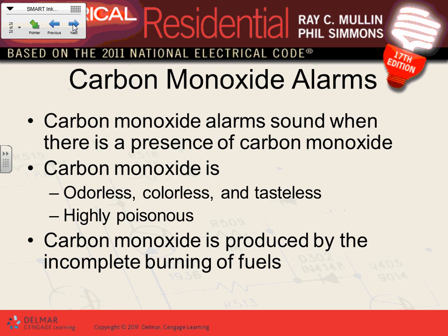Carbon monoxide detectors, guys, detect for carbon monoxide. I think in Minnesota, it's required at least once in the building. One of them in the whole house, in dwelling, it's required once. It could be plugged in or hardwired, but you have to have 2 sources of power for it. If it's plugged in, it has to have a battery. If it's hardwired, of course, it has a source. It protects you from this deadly, Jeff said it's myth, carbon monoxide.